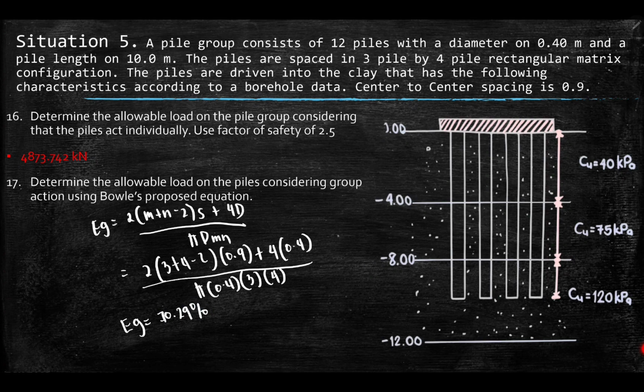Okay? So this is not the final answer pa. Ang tinatanong is determine the allowable load on piles considering group action using Bowles proposed equation. So when we talk about the allowable load, ang gagawin lang natin is to multiply this efficiency to our allowable load na individual piles lang na walang efficiency factor. Okay?